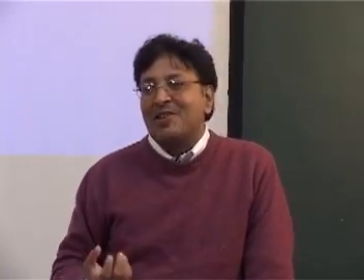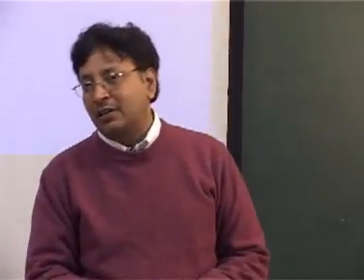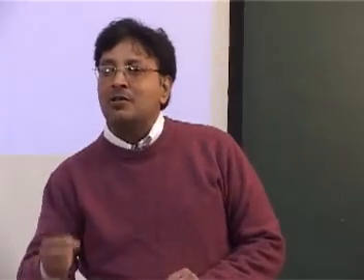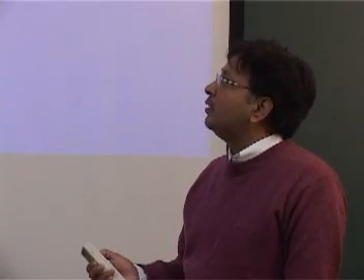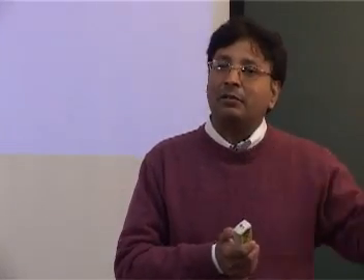Given a better name, because we want to call ourselves better, don't call us ignorant people, but say, let's take a safety. But essentially, I wouldn't say the factor of ignorance, but a factor to account for the ignorance. Let's put it this way. When your knowledge is very good, your instruments are very good, the factor of safety can be smaller. Or when your instruments are very crude and we don't know, so let's be safe, then the factor of safety will be large.